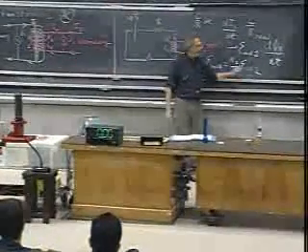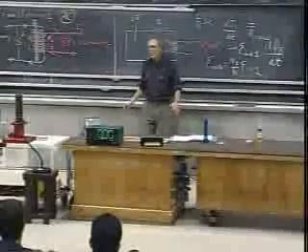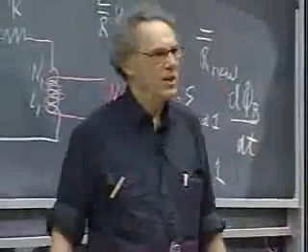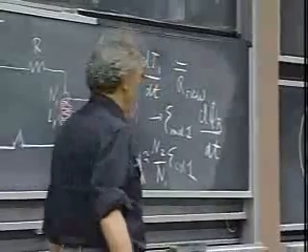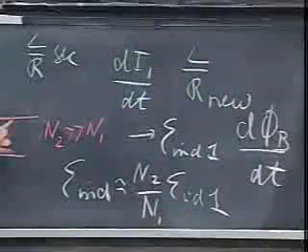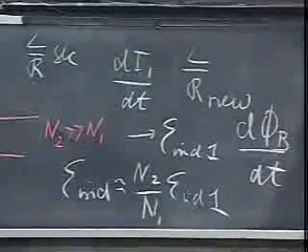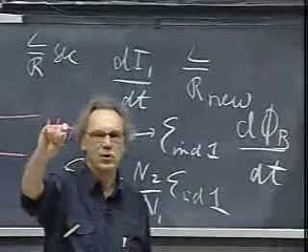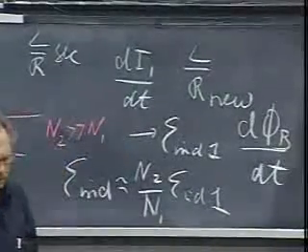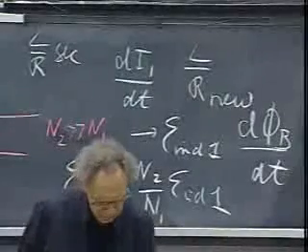So now I get in the secondary an absolutely horrendous potential difference. I could get up to 1,000,000 volts if I want to. In your cars, that is not necessary. It is enough in your cars that you get something like 10 kilovolts. And that will comfortably give you a spark over your spark plug.